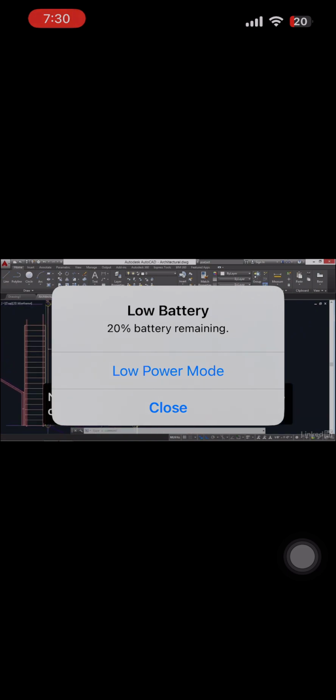Now copy works very much like the move command. The only difference really is that it leaves the original object behind. So let's try copy. I'll select this lounge chair and press enter. At this point, it looks identical to the move command. It says specify base point. I'll click some arbitrary point. I'll move the cursor to the right and click again to specify the second point. Then press enter to end the command. So I've essentially moved this over and left the original behind. That's essentially what copy does.